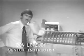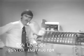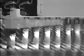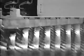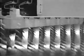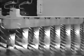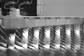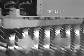In the previous lesson, you saw how the compressor was able to compress air while maintaining a constant airflow velocity. When the engine is running at normal operating speed, the stages are matched perfectly to accept the compressed air, multiply the pressure by a small amount, then pass the air to the next stage. But at lower speeds, the stages are not matched. The forward stages produce more airflow than the rear stages can handle. The rear stages become temporarily blocked, unable to move the large volume of air out of the compressor. The flow velocity drops, causing a stall condition.